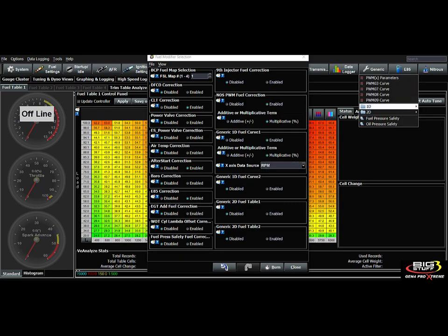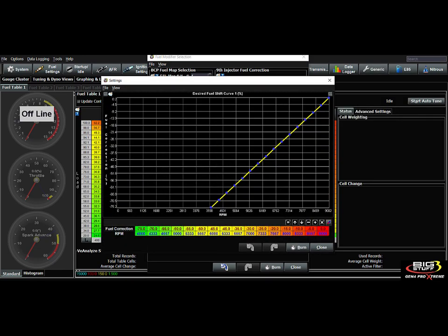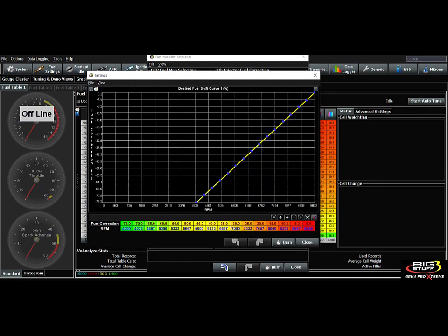So if I come back over here and go in the fuel curve here, I'm going to say, okay, in this example, I'm going to go from 4 to 9,000 RPM, but I want to do a fuel percentage. So let's just say I want to add 15% at 4,000, and let's see, at 9,000, I want to add 25%. I'll just highlight that row and interpolate it. And this is now going to provide a fuel correction based on this RPM.